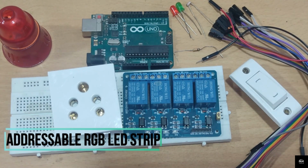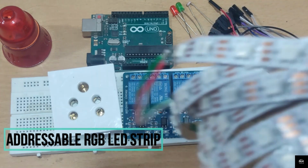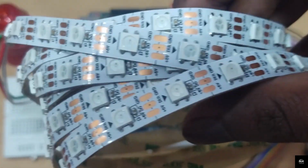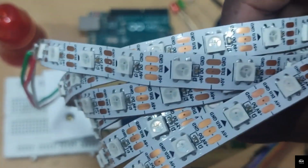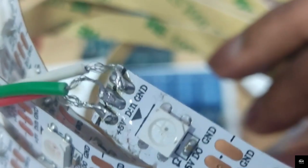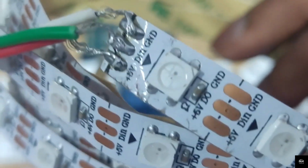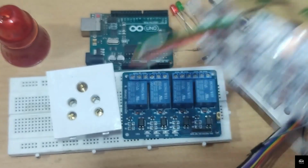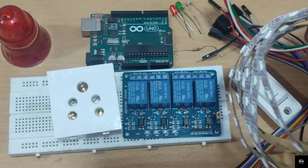And after that, we are also going to be needing an addressable RGB LED strip. You can see this is the addressable RGB LED strip that I'm going to be using. You can find it on Amazon easily, and the details about it are given in the PDF. There are in total 3 pins on this LED strip. The first one is 5 volt, the middle one is the digital pin, and the third one is the ground. Using this addressable RGB strip, we are going to be controlling it with our Arduino board. So let me put it aside.